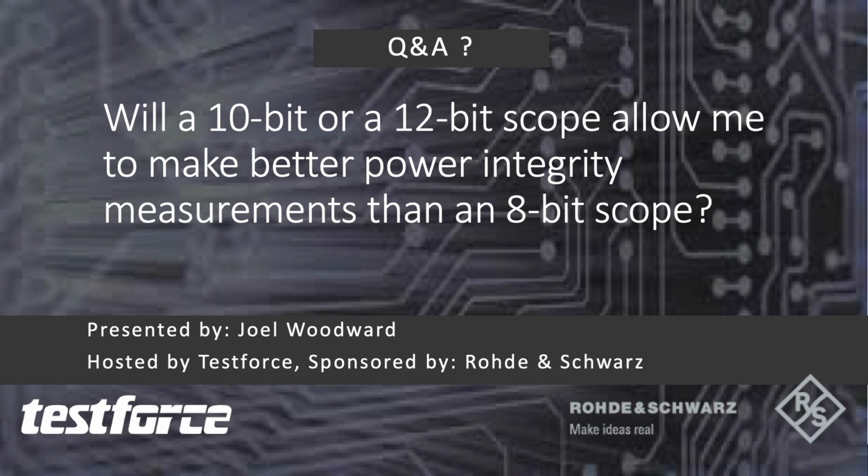You bet. The very first question is, will a 10-bit or 12-bit scope allow me to make better power integrity measurements than an 8-bit scope? The answer to that is it depends. Typically, when we're looking at the very, very small amount of peak-to-peak voltages on a power rail, it's noise that dominates the measurement and not the resolution of an ADC in an oscilloscope. So it's the noise associated with the oscilloscope rather than the ADC. So it depends on the oscilloscope and how much noise it has. But typically, all three of those will produce results that are more dependent on the noise associated with the oscilloscope than the ADC resolution.